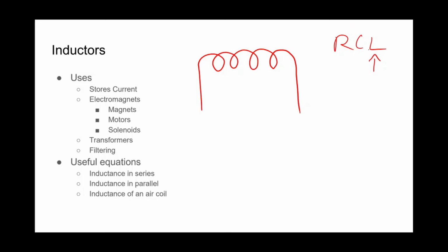So if we want to talk about this, I'm going to go like this. So pick this one first, pick your capacitor second, and pick your resistor third, because cost goes up this way and accuracy goes up this way. So it's far easier to pick an inductor and be like, wow, this is 20% off of what it said it was going to be. The capacitor is going to be like 10%, and the resistor is going to be like 1 to 5%. So choose your inductor first, your capacitor second, and your resistor third.